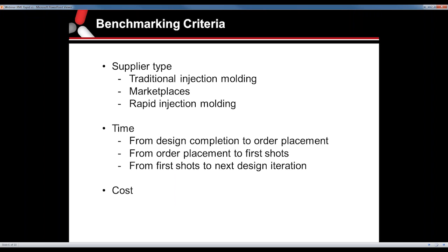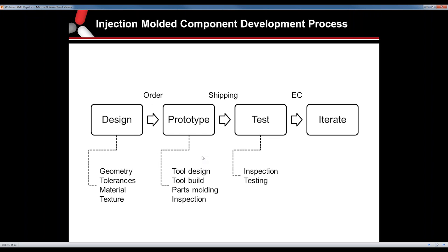Anything you guys want to add to that? Well, just at that end phase there, it's the key part. All of it's key, but when you get to the testing, the tryout stage, you're doing your fit and function, making sure the part is working the way you want, mating with other pieces, and then the task is to make small changes to materials, parts, the tooling itself, to get you to a tighter tolerance on the part that you're trying to create. Okay, good.